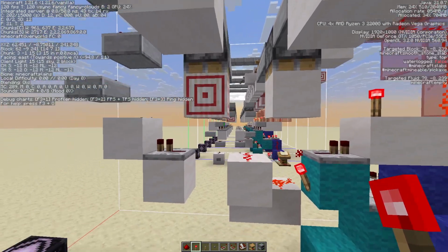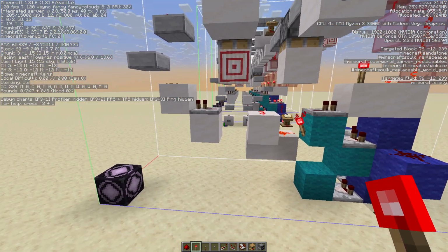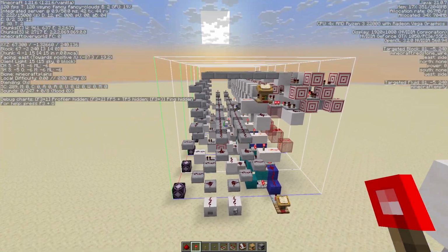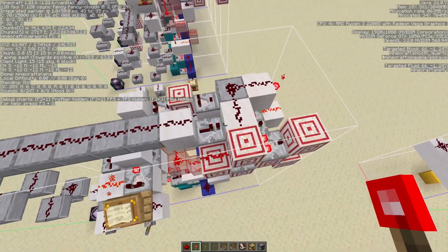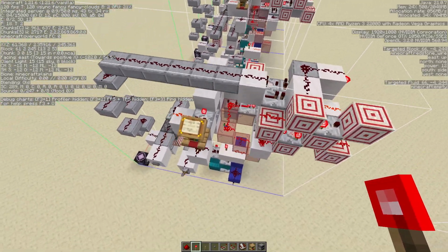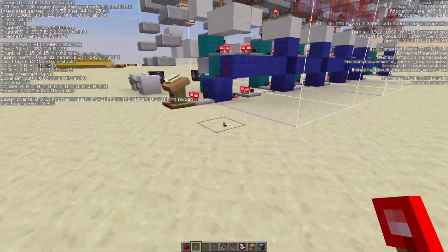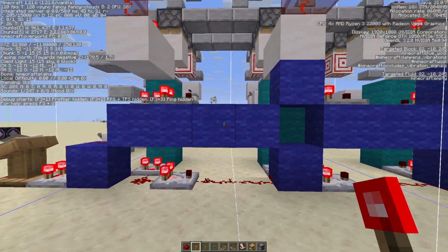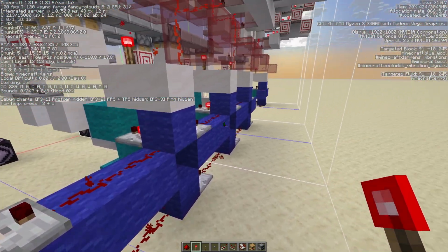or you set the flash or the right line, dropping this, powering this, going all the way up, and flashing what's on the data bus onto the register. You can stack them, and then the addressing actually looks like this. This is the start. It is important that the start is different from the rest of the addressing line.